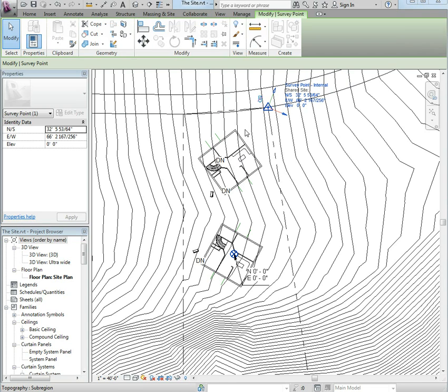What actually ends up happening, instead of doing what you would hope it would do, which is basically to update everything so that this was now correct, is that it moves the marker icon with respect to the shared coordinate system, updates these numbers that you see over here to reflect that fact, and then nothing else happens. Your spot coordinates don't change because they refer to the shared origin. The linked files don't change. Nothing changes except that the icon is moved, which is bad because nothing else is updated. In other words, you really shouldn't ever move the survey marker with it unclipped.